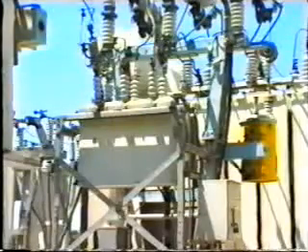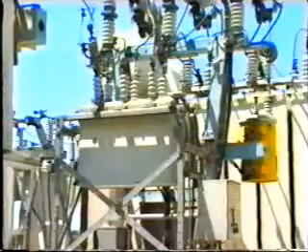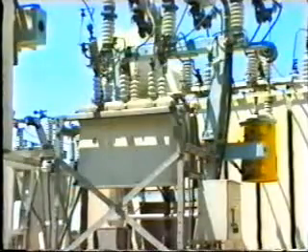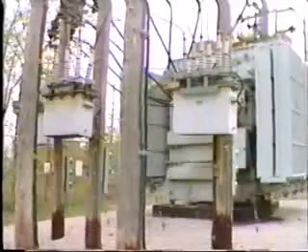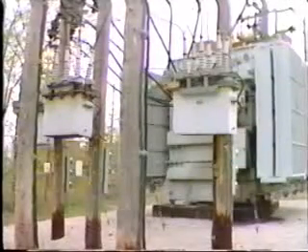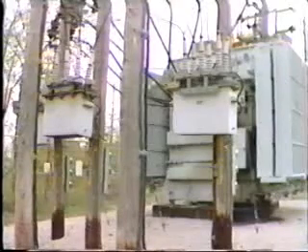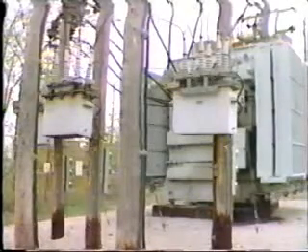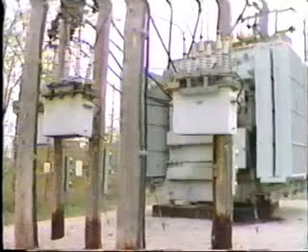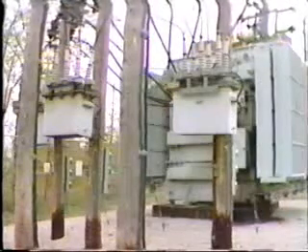Again, all of the settings need to be coordinated with other protection devices on the feeder, particularly the feeder breaker. Actually, the operation of reclosers on the distribution system does not really affect the stability of the power system very much. They are installed with the objective of reducing outage time to the customers.